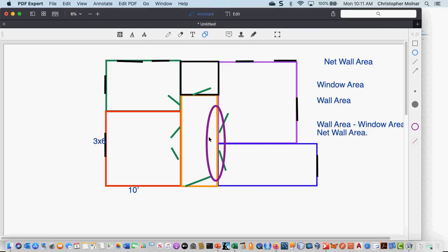Now, there's one area of any house to be worried about. If this is a garage, and if I do not heat or cool my garage, these walls right there are insulated. They're considered outside walls. So what we're worried about is the heat transfer through any wall that is not abutting heated or cooled space. Are there any questions on that?